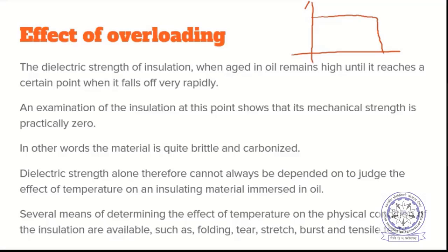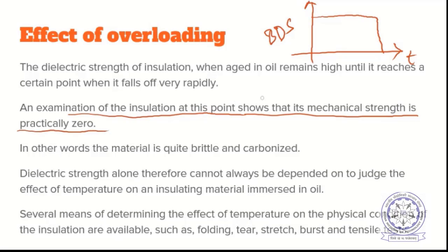Breakdown strength, BDS versus time. When a paper or press board is immersed in oil, the dielectric strength behaves like this. Examination of the insulation at this point, where the dielectric strength suddenly falls, shows that its mechanical strength is practically zero.